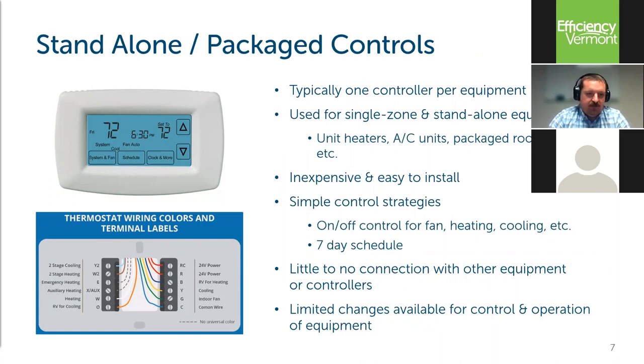You would see it very common to use the traditional thermostat wiring. So you had fan call, heat call, stage 1 and 2, cooling call, same thing. And a lot of the control tended to be very simplistic, kind of on-off control. I could turn things on and off, but I couldn't really adjust things. I couldn't modulate things unless I had additional components. A lot of these programmable thermostats also had a 7-day schedule. So you would have to change for daylight savings time, leap years, that kind of stuff.